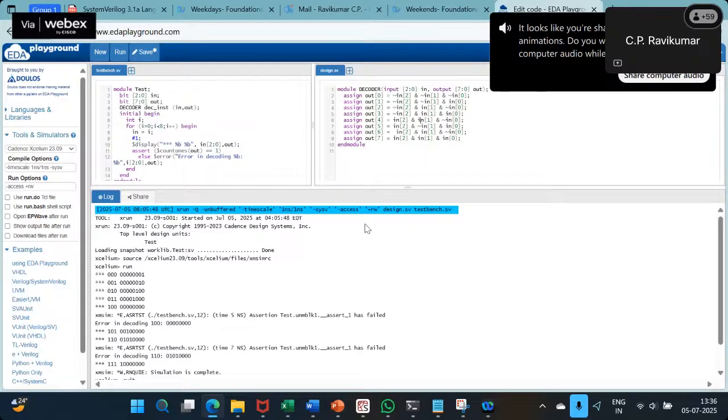Yeah, that could happen. See, when you put 110 in my current logic, what is going to happen is 110 will also generate, and 100 will also generate. So that is actually correct. See, here 2 things are getting selected, and here nobody is getting selected. So it's actually correct. Okay. So that is what I meant by assertions. They have provided some such functions like count ones to make your life easier.